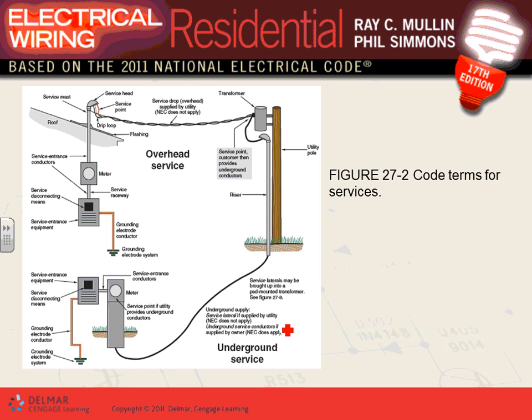Here's the single most important thing, guys, when it comes to the service for a dwelling. This is the transformer where the utilities will provide the power for you. I want to bring to your attention a very important thing: the service point. Can you guys see it right here? I want to highlight this point. Whether you're going overhead or underground, the service point is right here. Can I get you guys to understand that one?